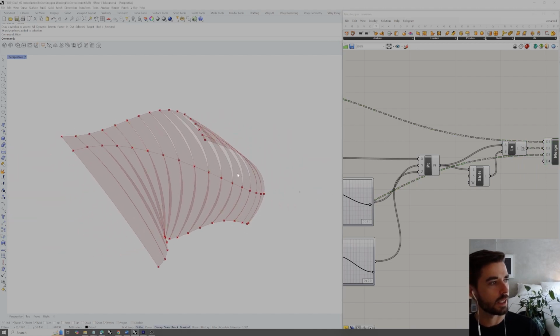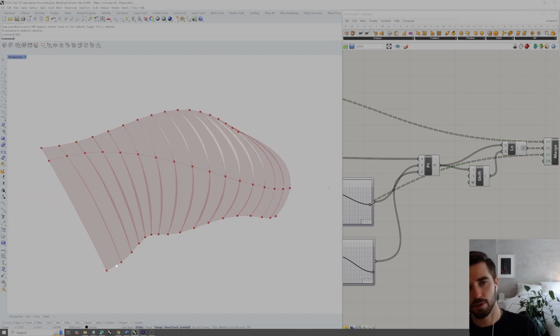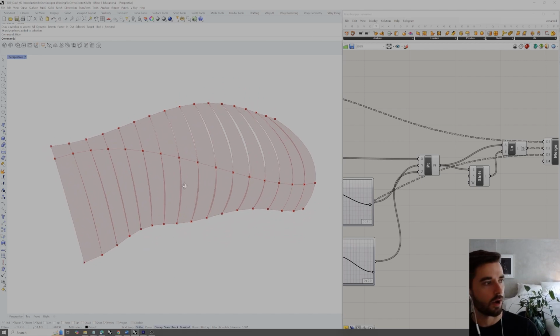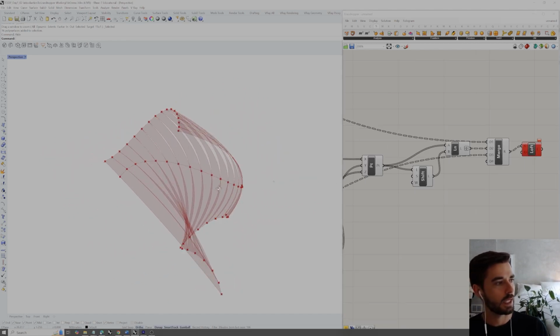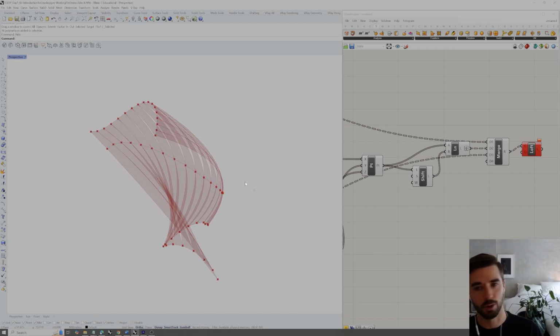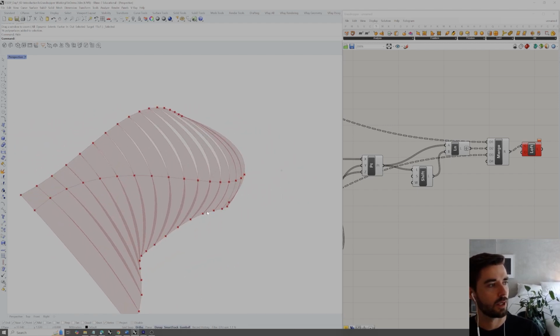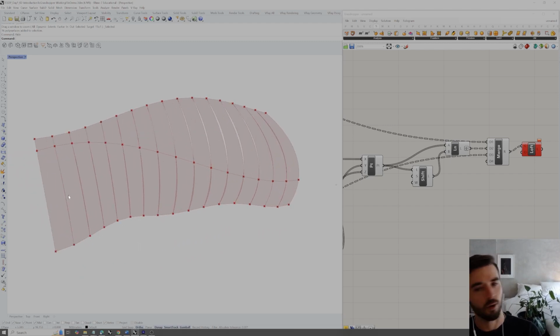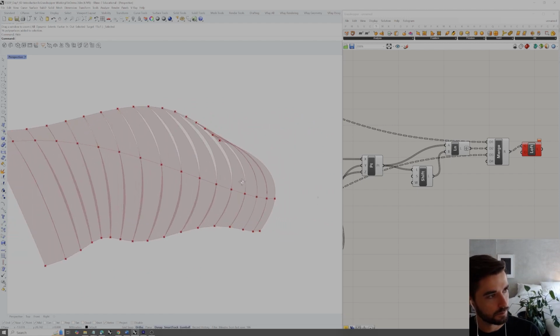And now you can see that each of these panels is drawing from the first line in the first curve, or first set of points, to the first line in the second set of points, and the first line in the third set of points. So we have these kind of complex sweeping lofts, and that's because our loft option is not straight sections, but instead the loft option is the normal, which is what it's called, which projects a smooth surface through all three of those line sets.